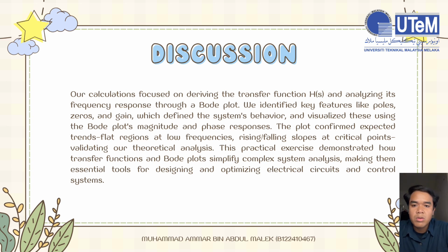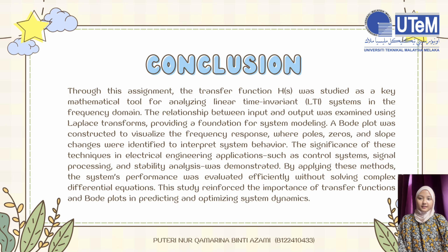Okay, let's go to the conclusion. In this assignment, the concept of the transfer function in advanced electrical circuits was explored. The transfer function, denoted as H(s), was defined as the ratio of the Laplace transform of the output to the input, providing a mathematical representation of linear time-invariant systems in the frequency domain. The Bode plot was analyzed to visualize the frequency response of the system, showing how magnitude and phase vary with the frequency.